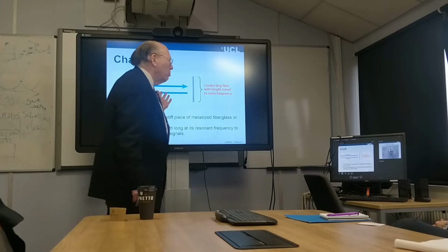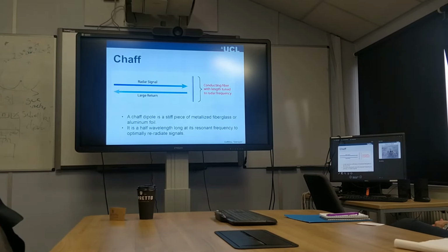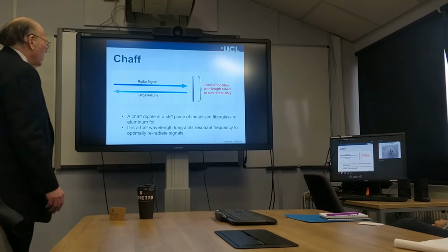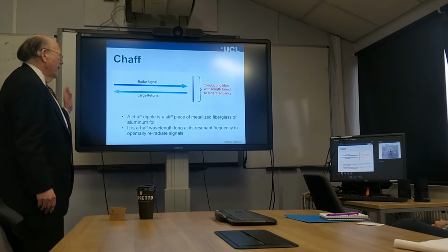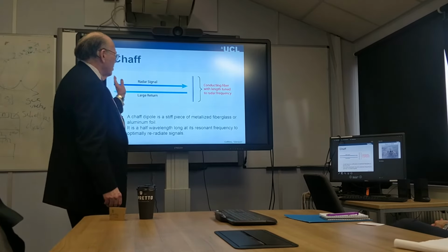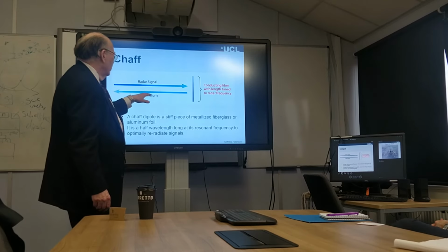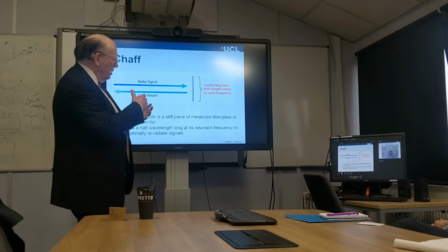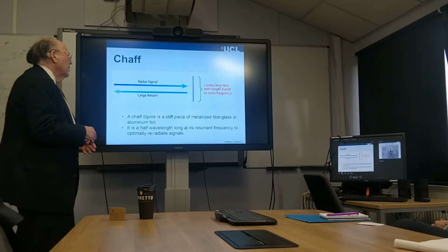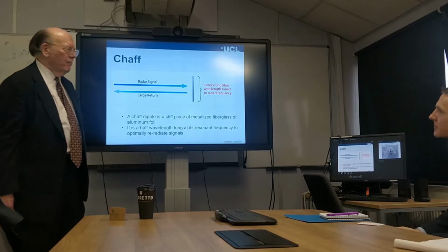All bomber aircraft are going to carry chaff, and a lot of strike fighters will have chaff as well now. They may only have a few bundles of it. This is basically the idea of how chaff works. The radar signal impacts the chaff cloud and it's scattered back. If the radar RF is within the bandwidth of that chaff, it's going to give a large return, so it's going to look like a big aircraft.